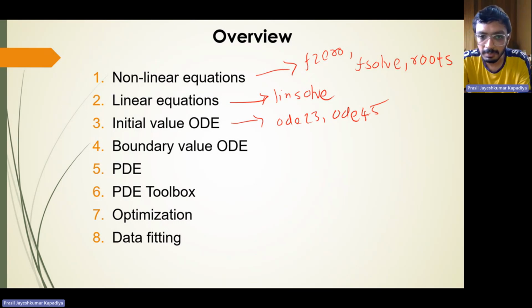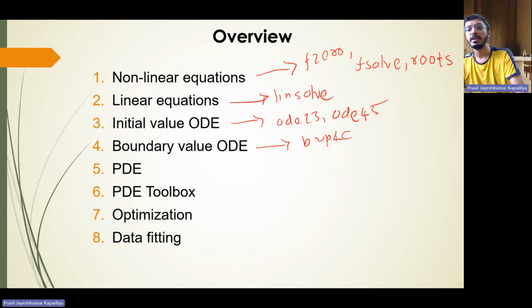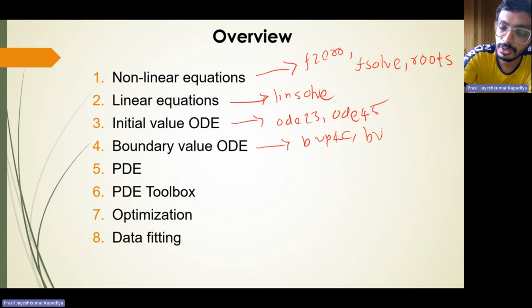Then we moved ahead with boundary value problems. For boundary value problems, we used bvp4c, MATLAB inbuilt command, to solve the problem, and to write down the boundary conditions we used bvpinit, MATLAB inbuilt command.